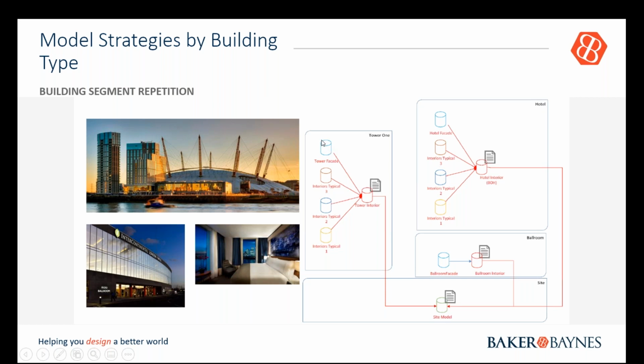We could create a model that has a complex facade, and maybe the interior items in a different model, and those can link together to create one building. The same with the other one, and these would all tie up and create one context central model. And these don't just have to be central models. This is just a good method or example for any linking of files at all.